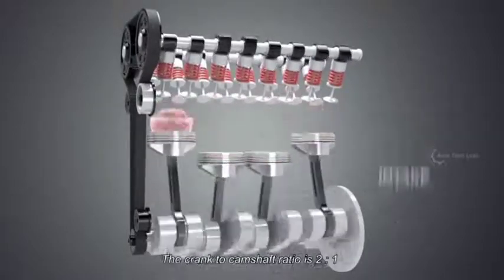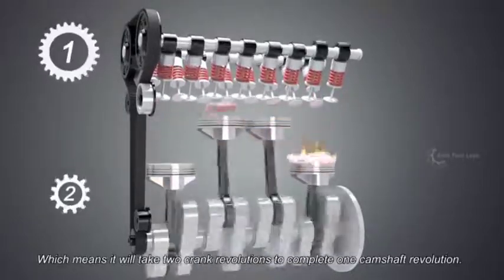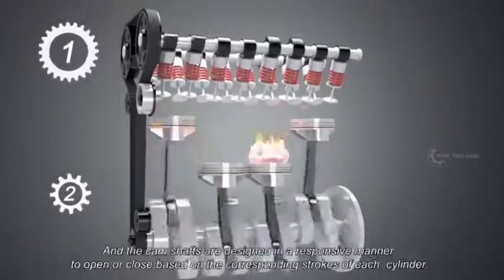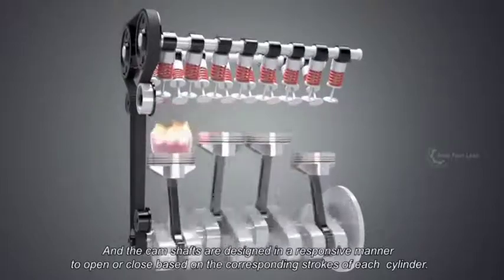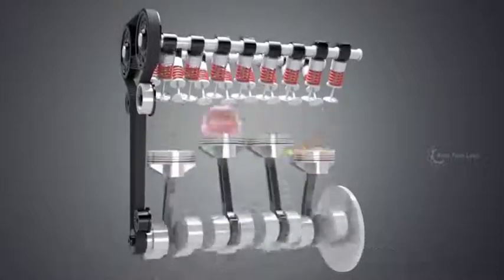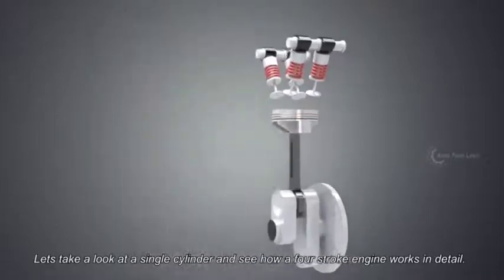The crank to camshaft ratio is 2:1. Which means it will take 2 crank revolutions to complete 1 camshaft revolution. And the camshafts are designed in a responsive manner, to open or close based on the corresponding strokes of each cylinder. Let's take a look at a single cylinder, and see how a 4-stroke engine works in detail.